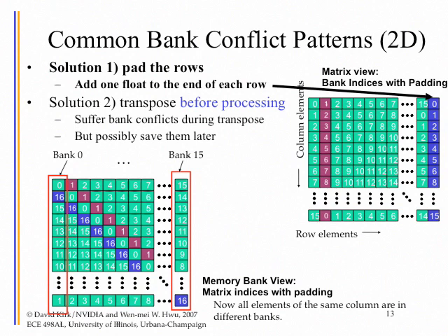As it turns out, this is not a new problem. People in computer architecture have known of this problem for at least 30 years. And a lot of the people in the 1980s, at this particular university, worked on different ways of building hardware so that you don't have bank conflict. One of the most popular approaches that industry uses today is randomized banking address assignment. So essentially, the address patterns get somewhat scrambled before they get placed into these banks.